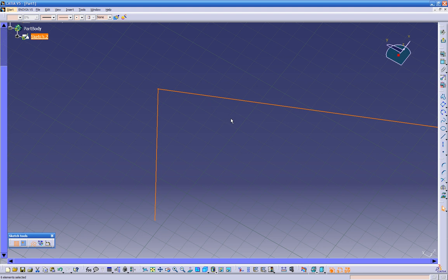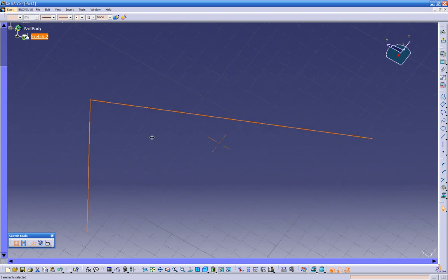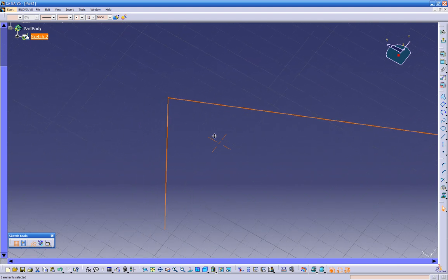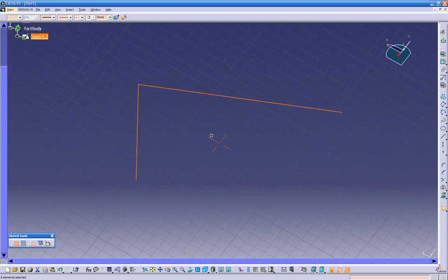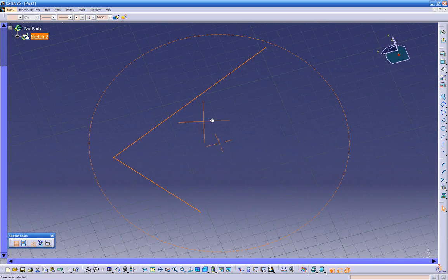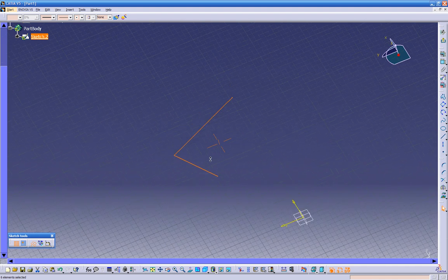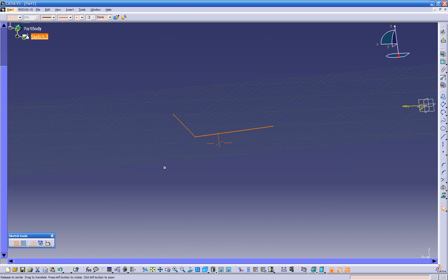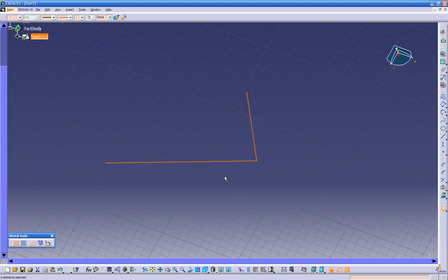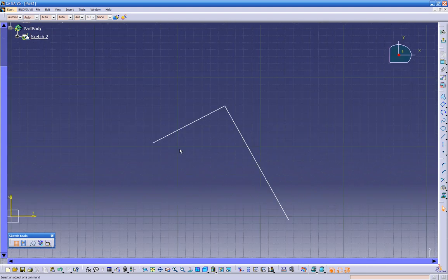And if I want to do the zoom in and out, middle button, hold down, ready for the panning. But if I tap right click on the mouse, just tap it, I'm able to zoom. So panning, rotating, hold both of them down, and tap, I can zoom. You'll probably get used to it by the time you get up to this point. So let's go back to the normal view.